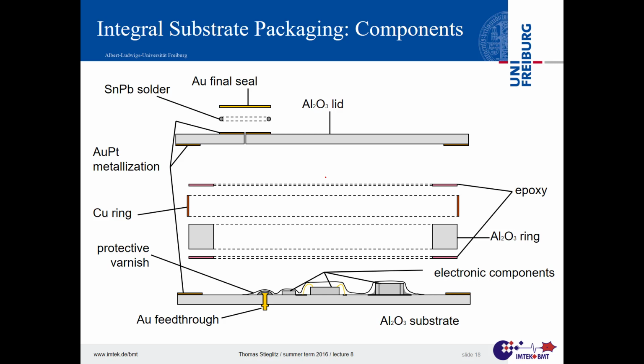I mean, we have a lot of silver in the new ones, indium, tin, silver, and they all tend to love dendrite formation. That means if you solder and you have a little bit of ions and a voltage gradient, they form structures like crystals and Christmas trees. And by that they can have a lateral outgrowth that short circuits adjacent lines.